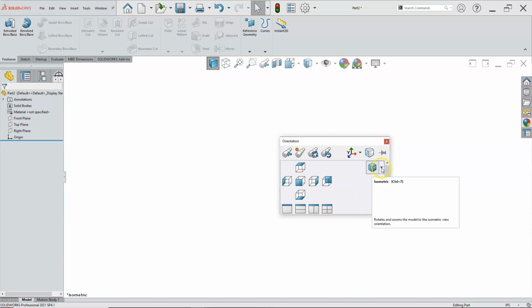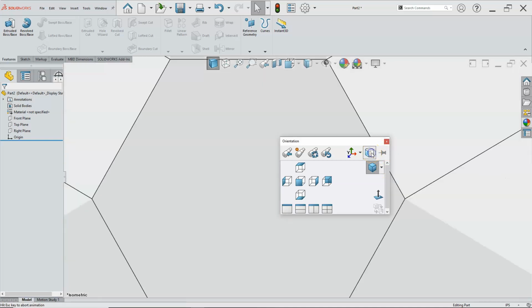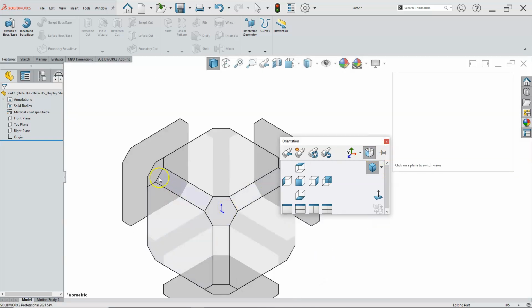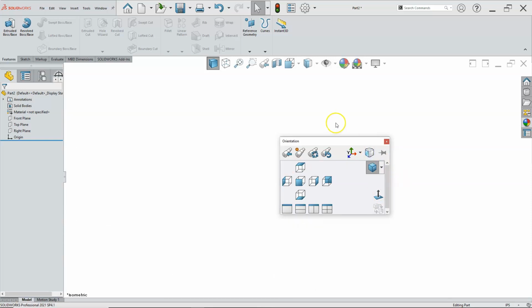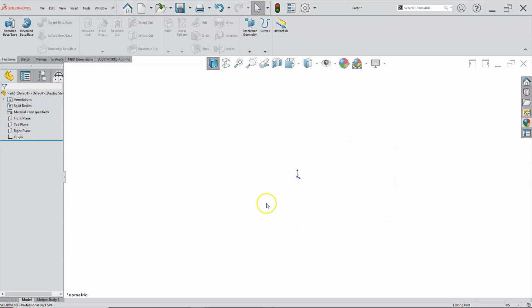And then some of the custom isometric, dimetric, trimetric, and normal to. Alright, so normal to usually needs to have a selection. Also, if you turn on the view selector, you're going to get the cube and be able to go through and select those items. And it's not something that I use regularly, so just kind of go with your personal preferences and what you'll use the most.